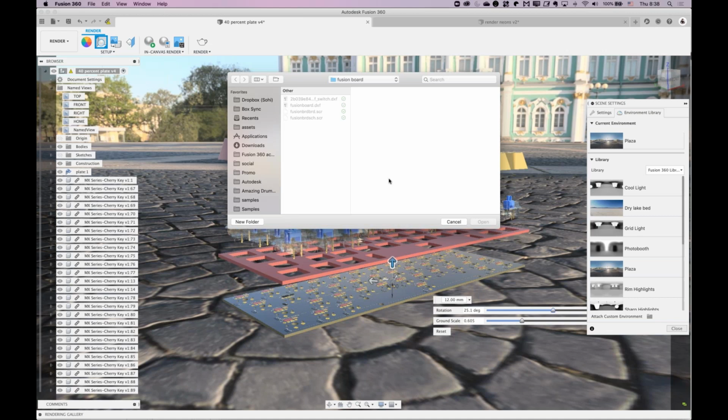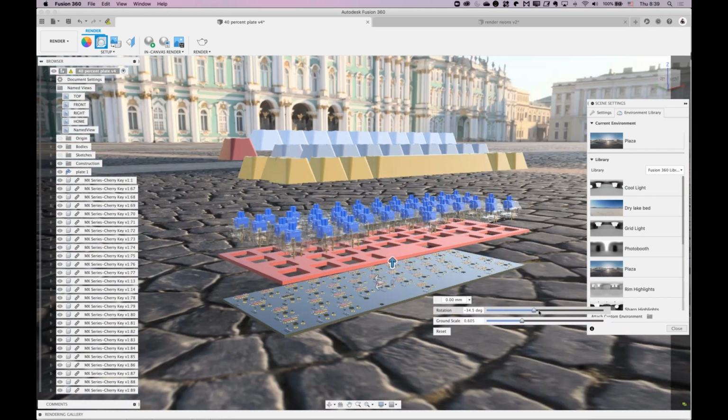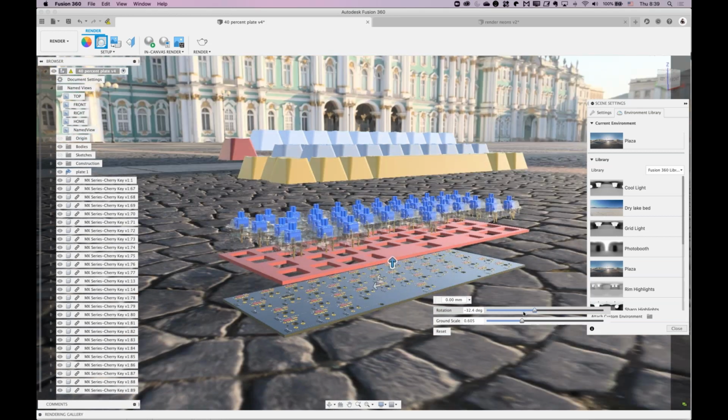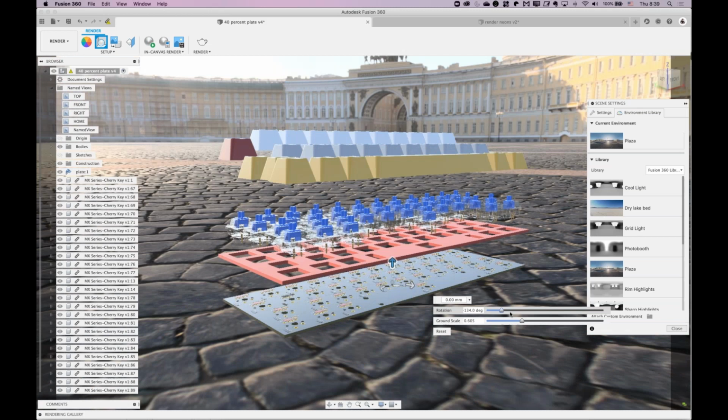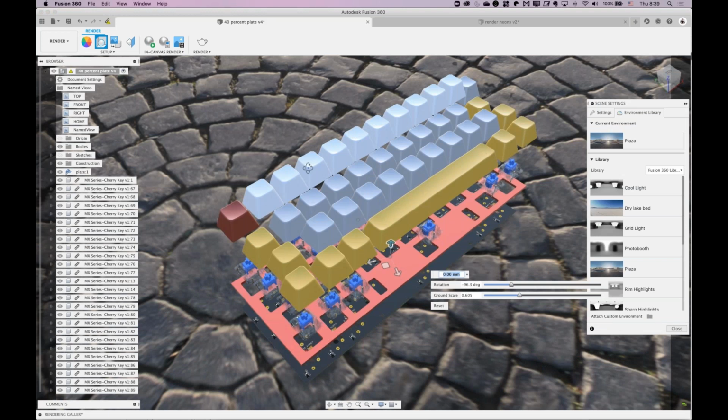So if you grab an HDR that you'd like to use, but the lighting is not all that great, the lighting is actually sourced from the white and the black areas of the HDR itself. So you can see in the thumbnail here that we have a 360 panoramic view of our environment, in this case the plaza, and there's a very bright area here, which is where the sun is, and that's actually where the light is hitting and is cast from. If I rotate this, you'll see how that light impacts it. So it's brightest there, meaning that as I tilt it around, you'll see that that's basically where the sun is. Yeah, so it's brightest on the back now there, based on that data.